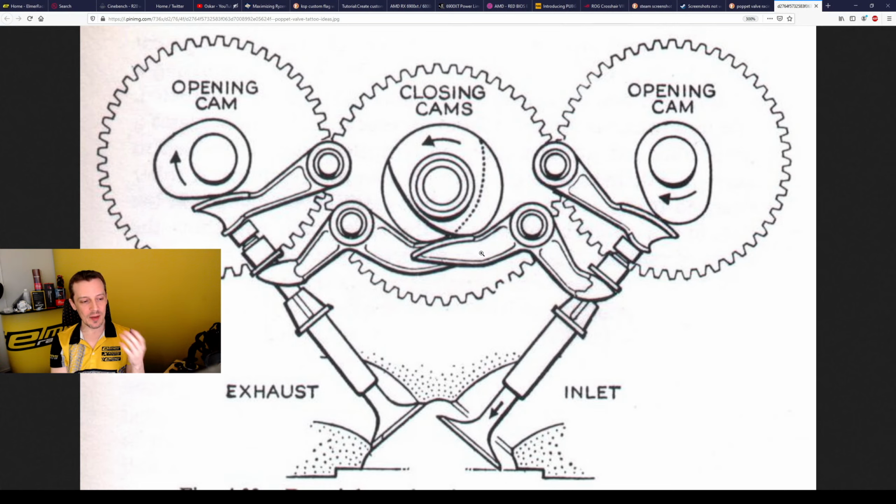So you need to do time dependent FEM over the whole cycle, and on the inlet maybe not so much, but on the exhaust, well, actually the closing side. On the exhaust part, you probably won't have much pressure difference when you're closing the valve. For highly boosted applications you will have some pressure differences on the exhaust side, or potentially on the inlet side also, but they won't be that big. So it shouldn't actually be that much of a problem. It's mostly just inertial issues.